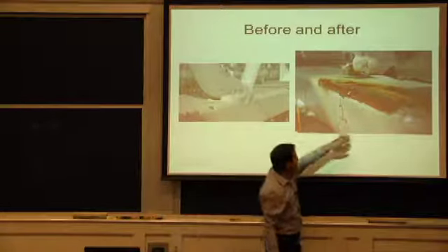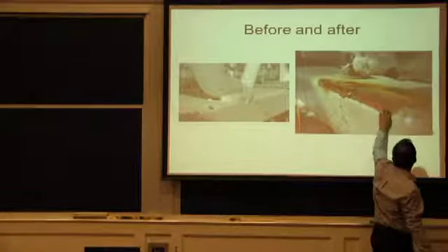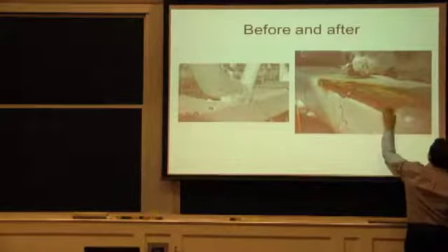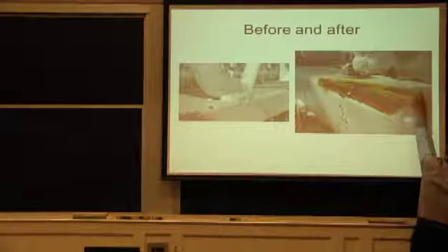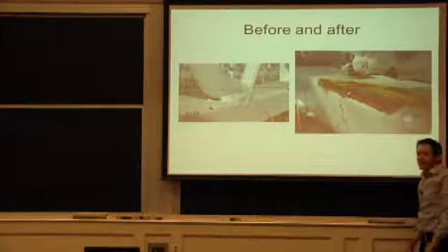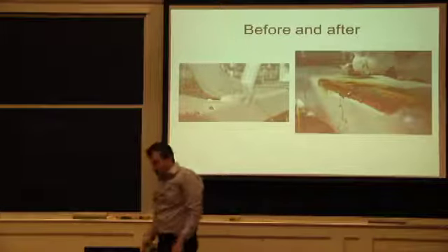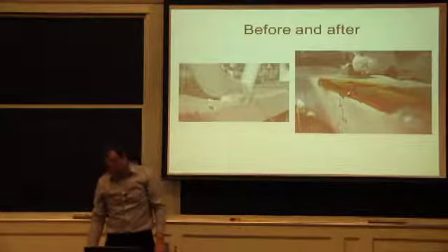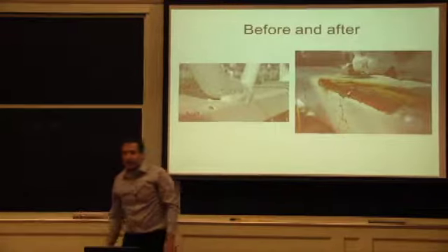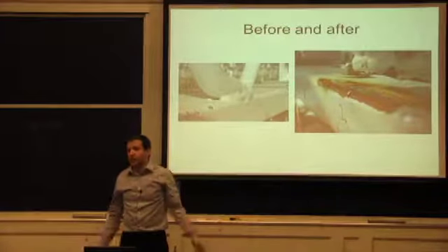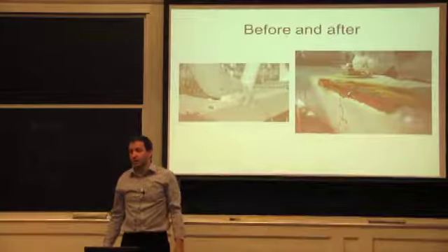You can see here, there's this little amount that's coming off here, the paint's coming off, and there was no weld further down the road on the other side of that round shape. So no redundancy and unknown capacity because it's a lot of welds. So how exactly are you going to go and inspect those?